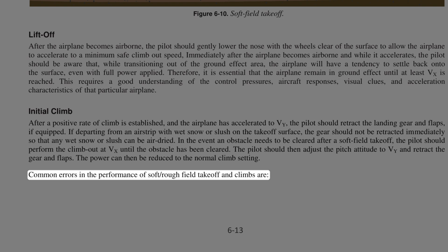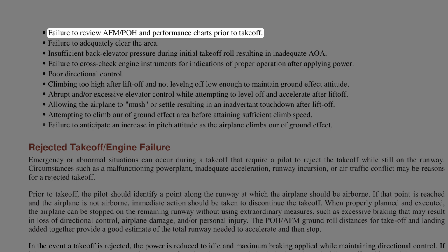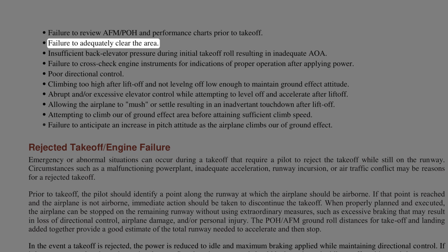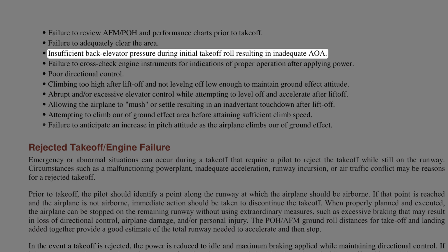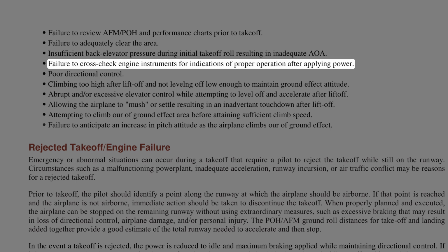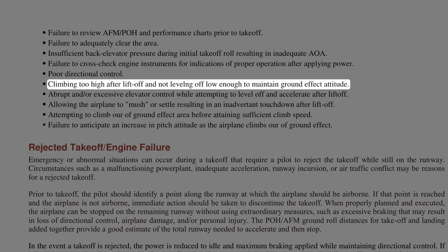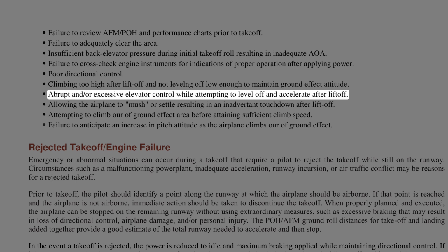Common errors in the performance of soft, rough field takeoff and climbs are: failure to review AFM, POH and performance charts prior to takeoff, failure to adequately clear the area, insufficient back elevator pressure during initial takeoff roll resulting in inadequate AOA, failure to cross-check engine instruments for indications of proper operation after applying power, poor directional control, climbing too high after liftoff and not leveling off low enough to maintain ground effect attitude,